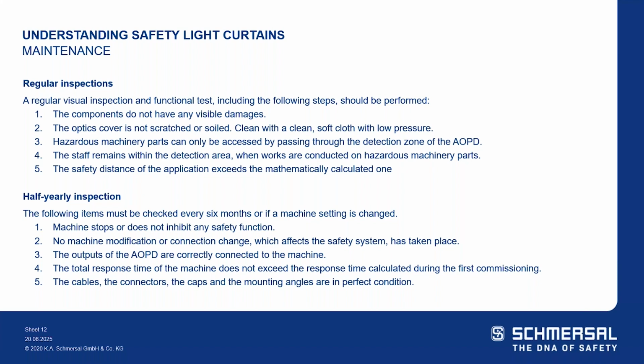The outputs of the light curtain are correctly connected to the machine and not jumped out. The total response time of the machine does not exceed the response time calculated during the first commissioning, and the cables, the connectors, the caps, and the mounting angles are all in perfect working condition.